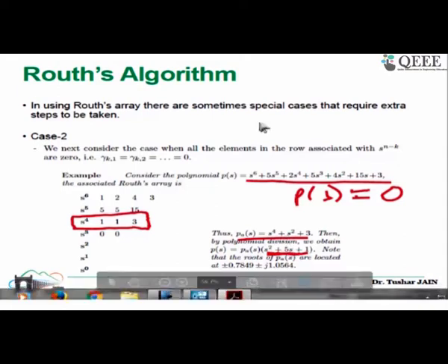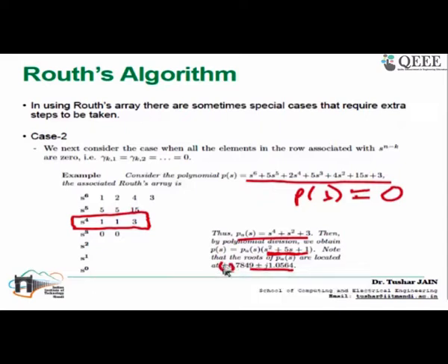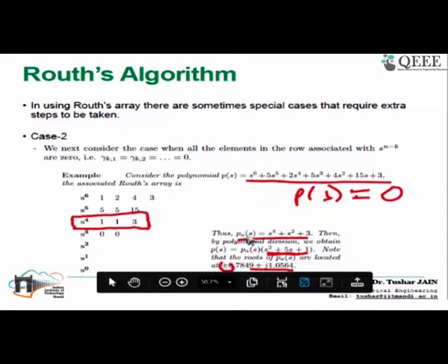But this is clearly visible in PA once you compute the roots: there are roots of PA located on the right hand side. The real part of the root of PA is positive, which says that the system having this polynomial in its denominator is an unstable system.